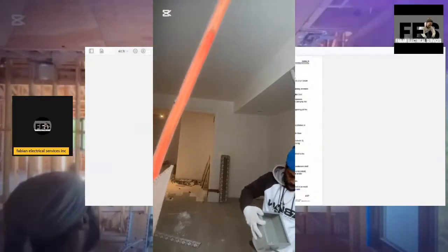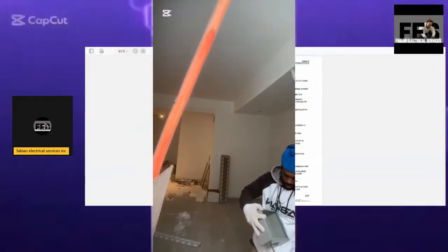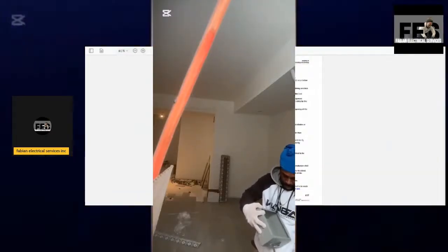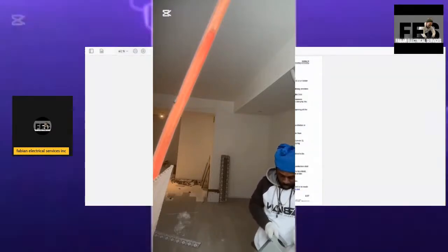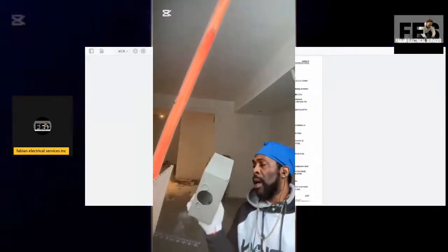when it's necessary. Again, for the installation, I'm not sure of the type of cable that I'm going to be installing as yet. The main service is a 400 amp incoming feed, and the whole home is probably not going to need to have the backup generator running, just the certain circuits that you need. It's all up to the individual if they want to have the whole entire home on the backup generator.